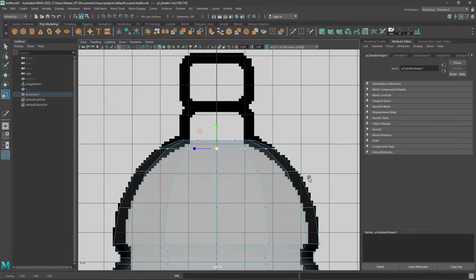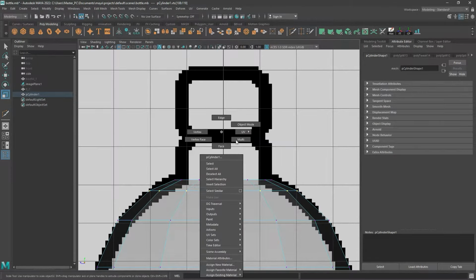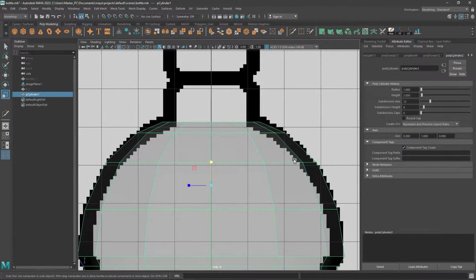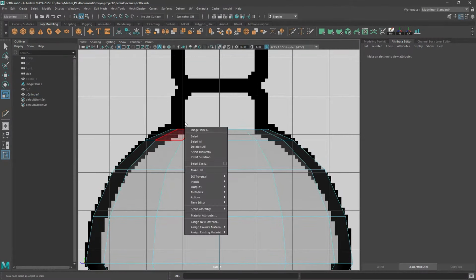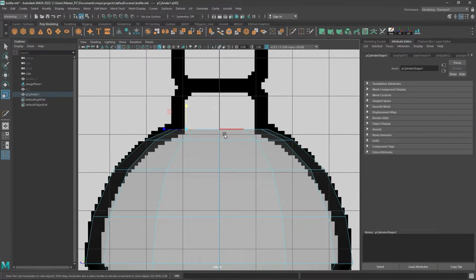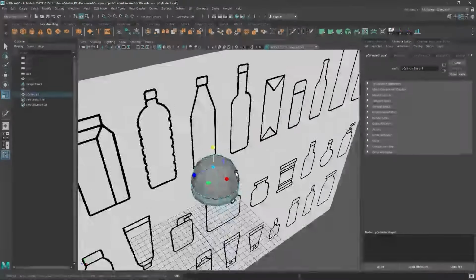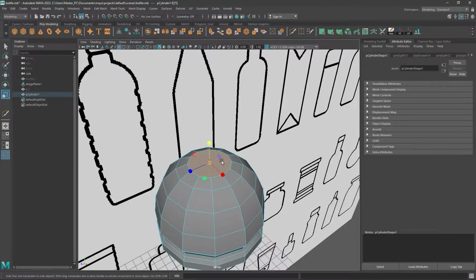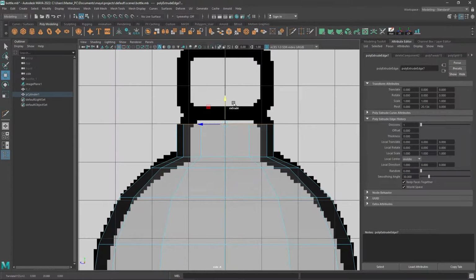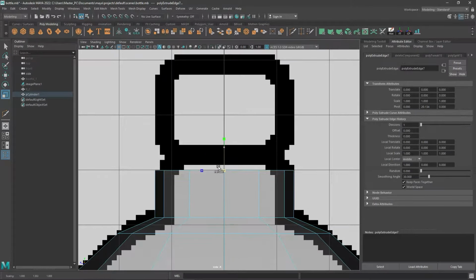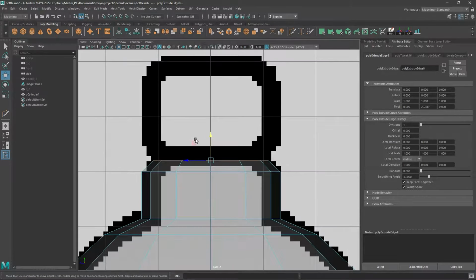Okay, you see it resembles a semi sphere. Okay, half of the sphere. Now I'm gonna select these edges. It's not gonna select. Okay, because of this I'm gonna delete that, and then double click, you can select it. Now I'm going to side view, extrude it, then I'm gonna extrude it again to the inside, then place it here. Okay, so we need to bevel here.